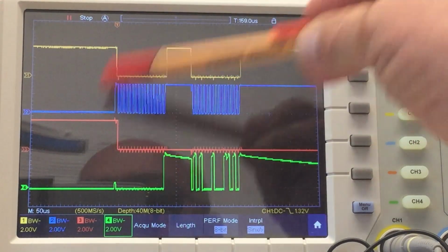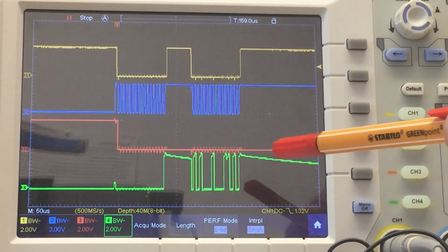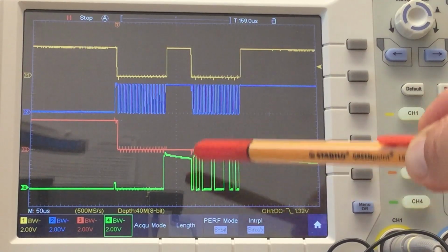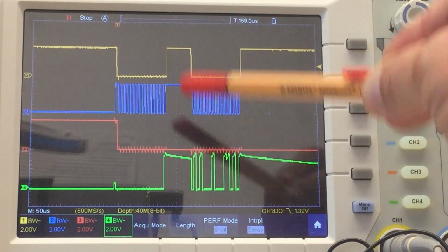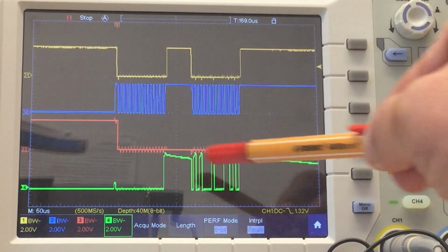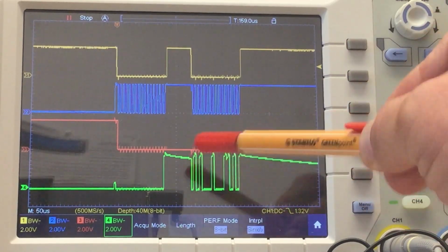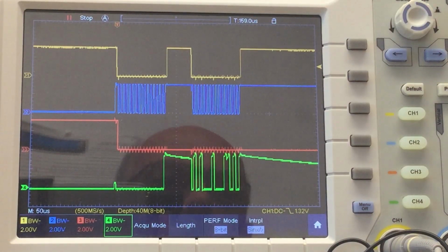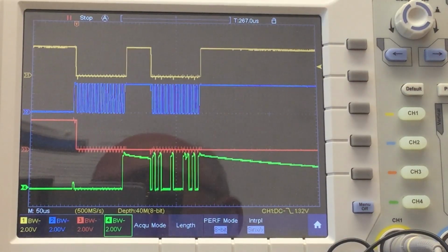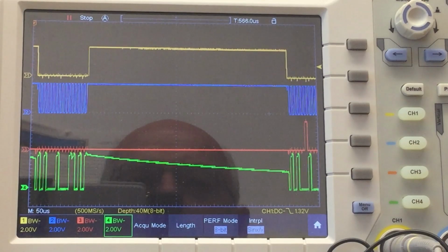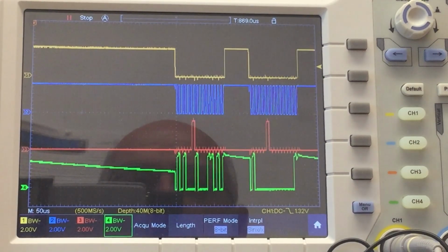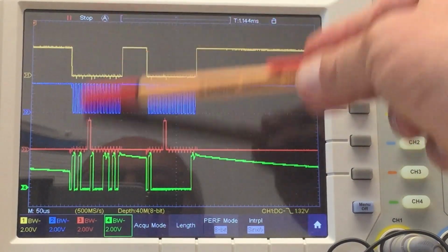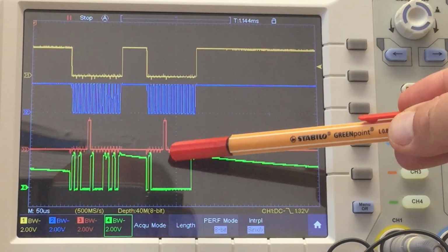Trying to read out the angle. And of course, I get the error flag here. That's this bit in the returned data. I also get an angle, but the general error flag is set in that transmission. And therefore, further down the road, I do what we've already done before. I read out the error register.